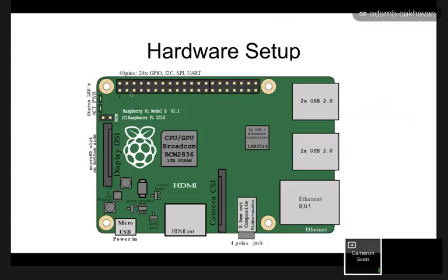But the main thing we're going to be looking at are these little pins called GPIO pins. They're called general purpose input-output pins. Essentially, each of these pins corresponds to an input pin or an output pin, and they could be both, meaning you can tell this guy to be an input or an output. You can use it to control a lamp or something like that, because all you do is tell your program to turn it on. But if you want to use it as an input, like what we're going to use today for a push button, it's going to say, I'm going to start reading in signals from this pin. Meaning if I push a button in the outside world, I'm going to know when that happened. So that's basically the inner workings of Raspberry Pi.